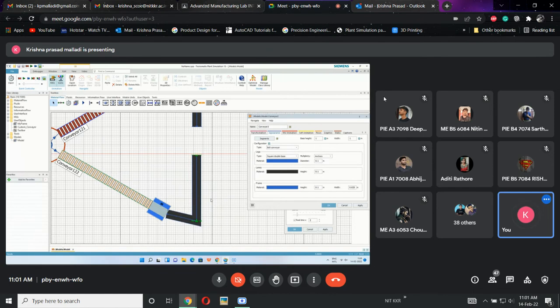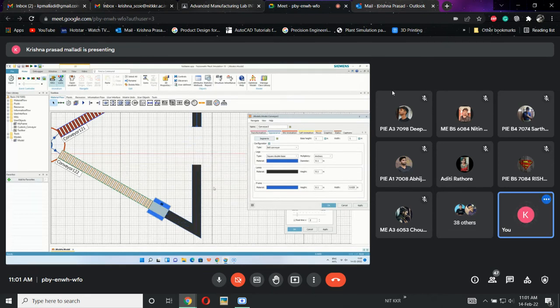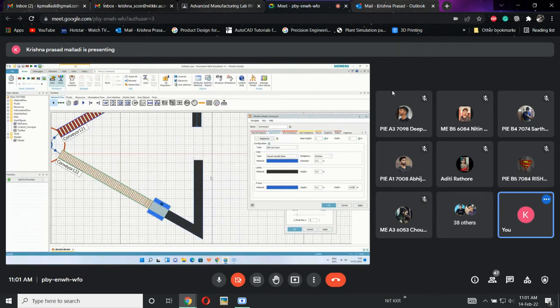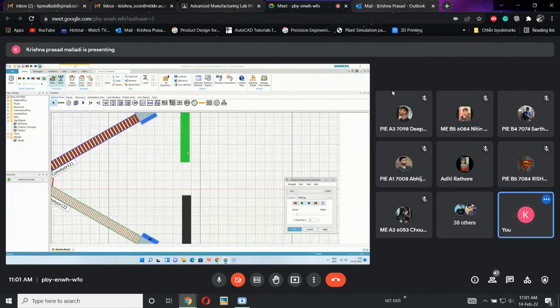Now if I change like this, what is happening? The angle is changing. So I don't want that. So I can check that also in the segments. Whenever I go with this one, change it please. Minus 120. Okay. Segments here, the length is 7. Instead of 7, I am changing it to 8. And this one, I am changing it to 4. 4 and 8.